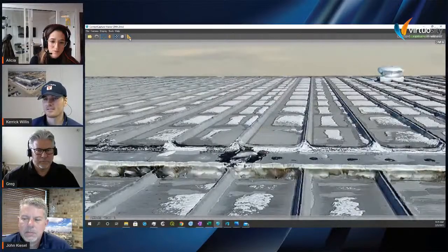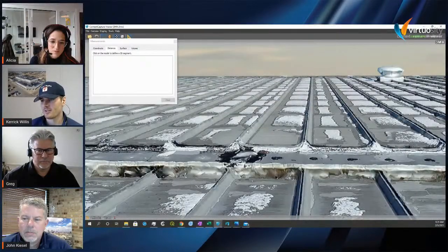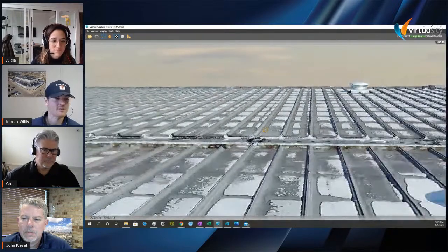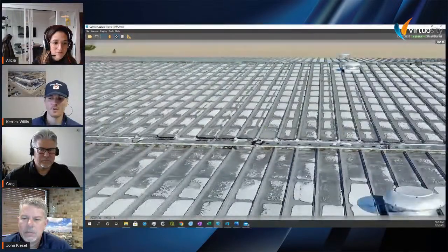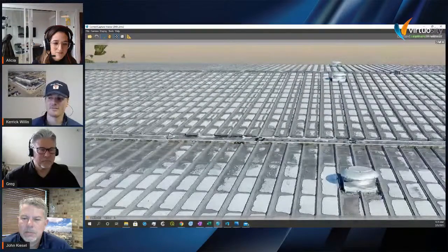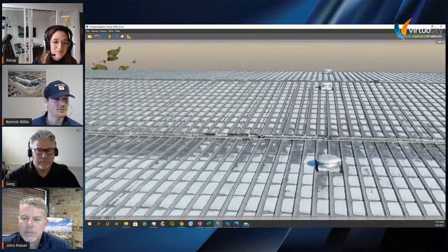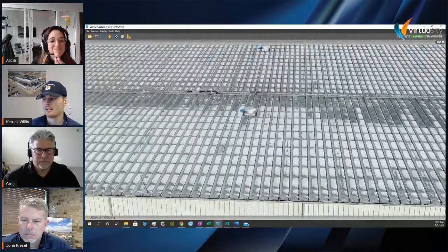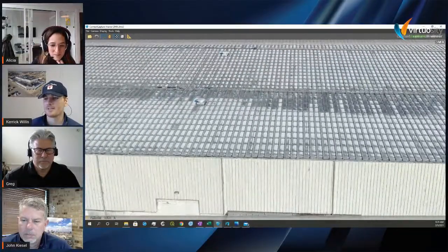Within the system, if you pull a measurement from the top of the rib down, you're at 2.14 inches, which is right at 2.5 inches. And then other places it's right about the same or a tiny bit more. And the panel measurement itself is actually 2 3/4. So it's normally within about a 1/4 inch on this measurement, which I think is very, very impressive, because it's a highly reflective metal surface. So it's something that, for most photogrammetry, normally doesn't stitch very well. Normally causes a lot of headache, a lot of problems.